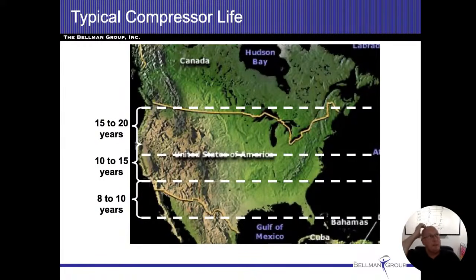All right. Lifespans in our area, and if somebody disagrees with me, that's fine. We usually tell our clients they'll get roughly about 20 years out of an air conditioning system. Sometimes we'll say 15 to 20 years. It depends on how much it's being used, how many heat loss days or heat gain days there are, which determines how long the air conditioner is actually going to be running.